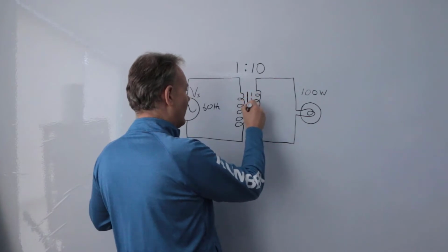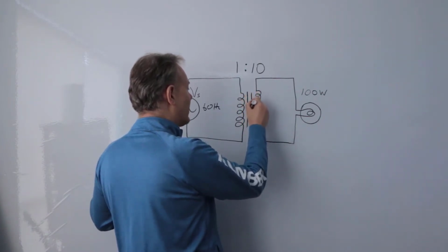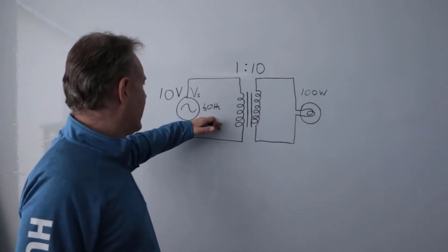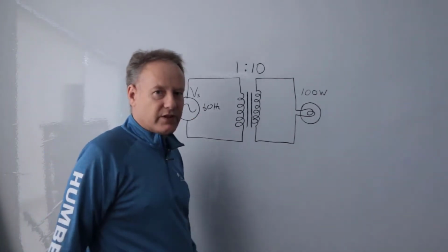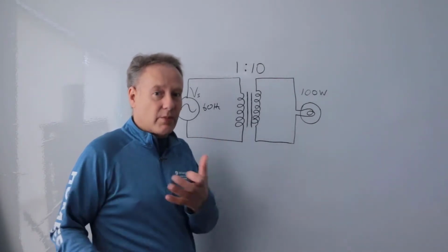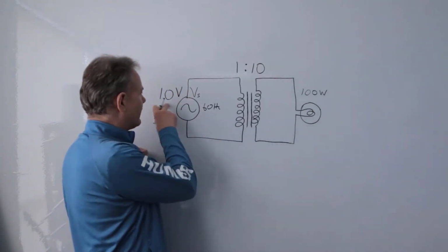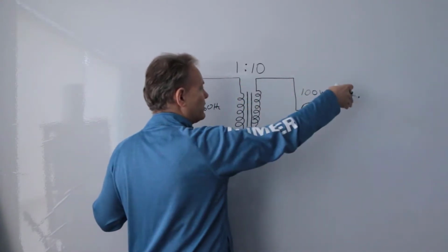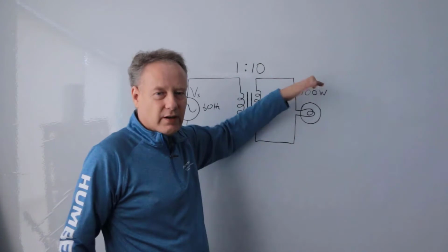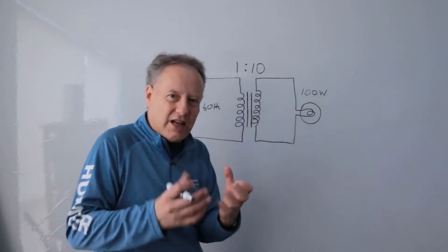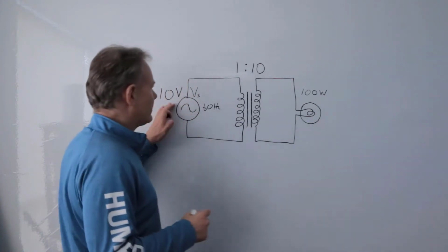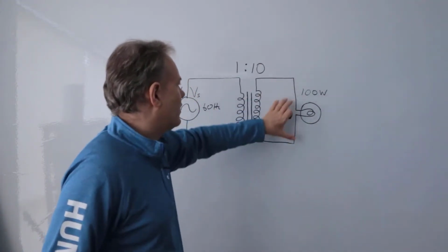frequencies. But anyway, I'm going to continue with this because this is a power transformer, and we're looking at essentially a 60 Hertz signal, something that we would see from the power system. Now, I've got this at a low voltage. It's a good number I can work with, and if I wanted to, I could make that 120. We do have a turns ratio of 10, so I'd actually have 1200 volts over here. But I want to work with more tangible values, something that we're used to working with. So I'm just leaving this with 10,